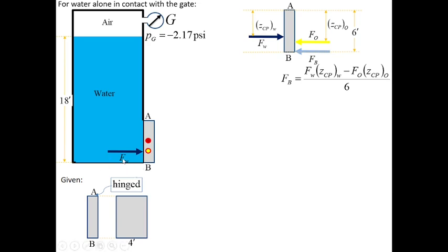Recall that the hydrostatic force is equal to the specific weight of the substance multiplied by h sub c, the distance between the free liquid surface and the centroid of a certain body, multiplied by the area.